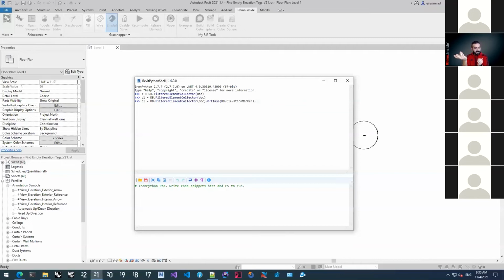So it also has a type. A wall has a wall type. An elevation marker that we put in a Revit model has an elevation marker type. Everything has a type. When you filter using a class, or let's say a category, a lot of times you get all the types and elements at the same time.